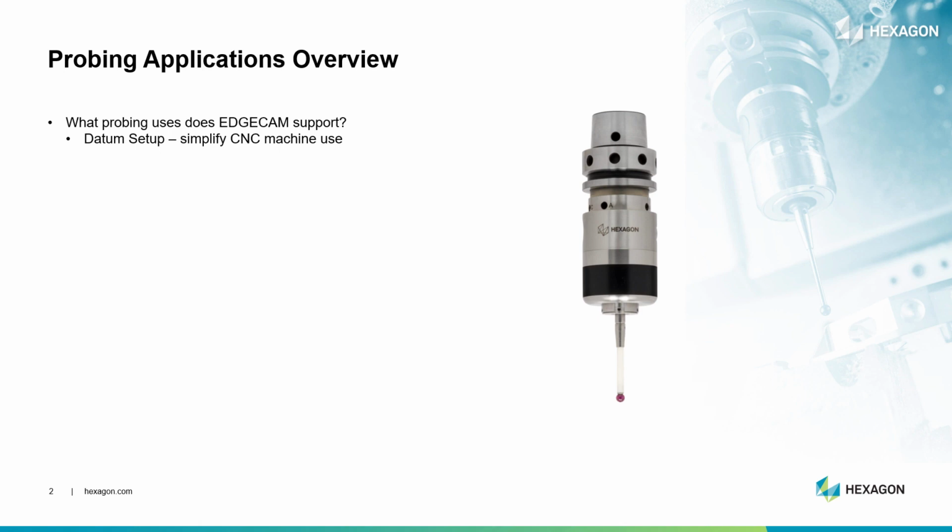Many modern CNC machines have onboard software to simplify programming and operation for this common task, but there's much more that can be done with a touch probe, such as measuring the machined part. This task is considered process security. Perhaps we simply intend to capture the dimensional inputs and store them for part certification purposes and quality assurance.